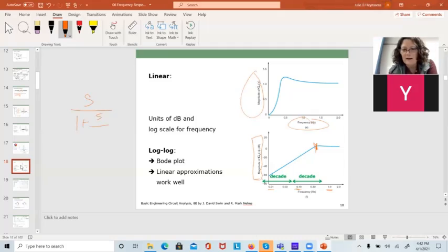And my omega naught here is 0.3. So 0.3 times 2 pi. That was a frequency axis. I can write the transfer function just looking at that. It's a high pass filter. You see things that look like high pass filters and low pass filters quite a bit.